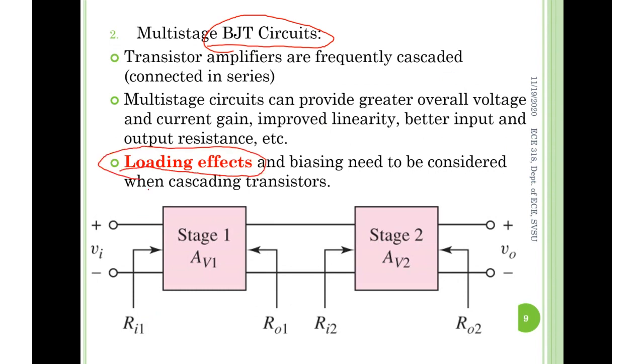Okay, so the input, this voltage amplifier, one followed by another stage. So the total gain is equal to the output voltage here divided by input here, right? And equals to what? The product between two stages' gains. Product, not sum. One of our midterm multiple choice, right?